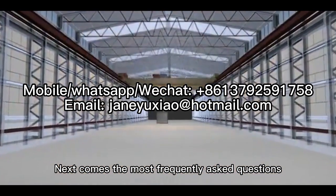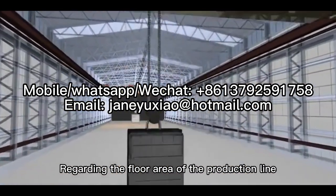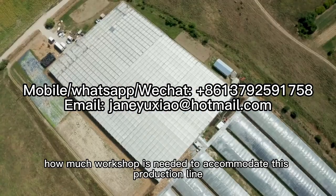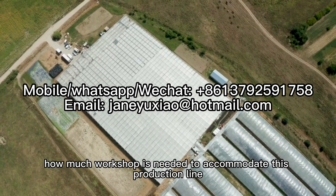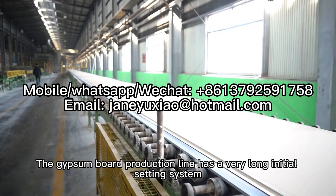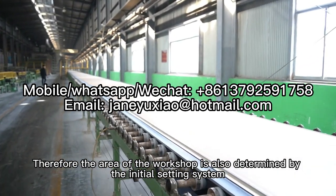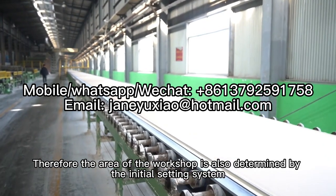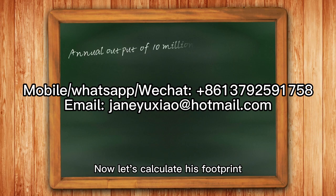Next comes the most frequently asked question regarding the floor area of the production line: how much workshop is needed to accommodate this production line? The gypsum board production line has a very long initial setting system. Therefore, the area of the workshop is also determined by the initial setting system. Suppose you need a production line with an annual output of 10 million square meters. Now let's calculate its footprint.